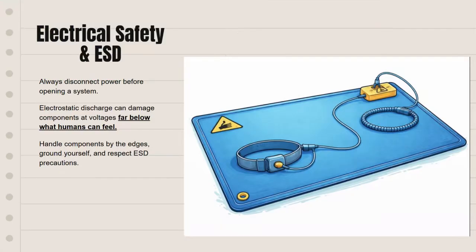Another thing to keep in mind is electrical safety and ESD. You always want to disconnect power before opening a system. Electrostatic discharge can damage components at voltages far below what humans can feel, so always handle components by the edges, ground yourself, and respect ESD precautions.